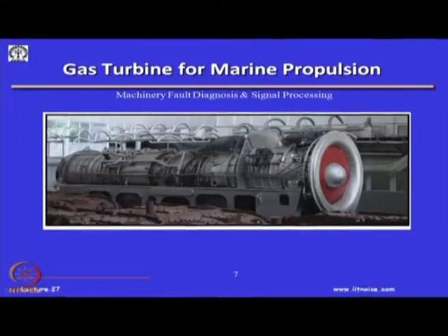And this has a low pressure compressor, a high pressure compressor, the combustor, and then a series of turbines, and each one of them has sets of blades. Okay. And so, how do you do the health monitoring of such gas turbines? So, the best place would be to keep vibration transducers along these rings. You will see a lot of these rings and braces are there, because you obviously cannot access them.